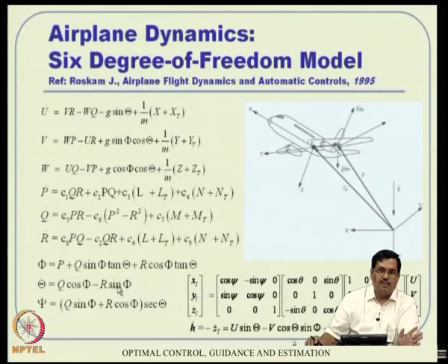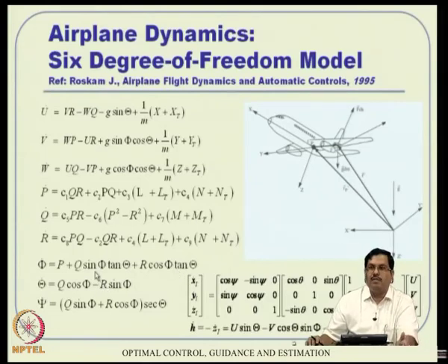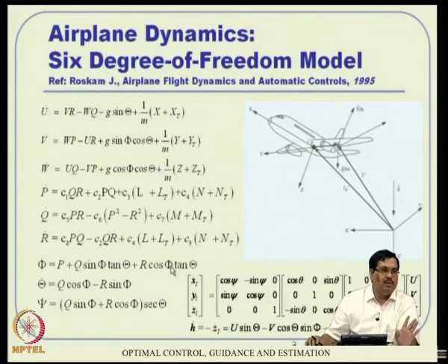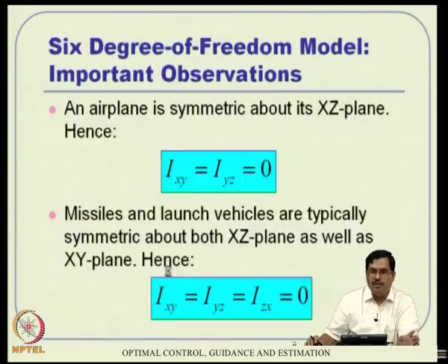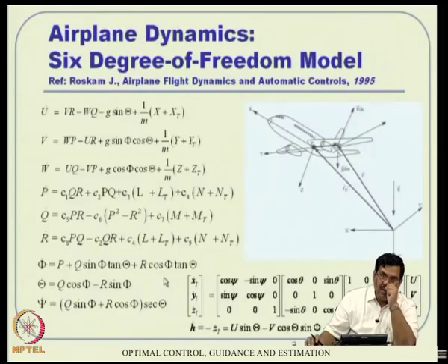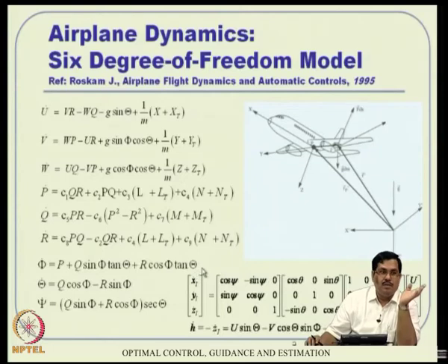The angles are okay, the angle values are fine, but the rate of change goes to infinity actually, which is not nice. And this rate of change is actually a function of the sequence of rotation. How you did that sequence of rotation, from psi, theta, phi. If you do a different set of equations, then the variable with tan theta will happen to be tan phi or tan psi. Okay, somewhere you will be getting locked actually. So there is no way you can get out of this mechanism actually. Okay, so that is where it happens, and this is actually bad because it happens at 90 degrees. 90 degrees is a small angle.